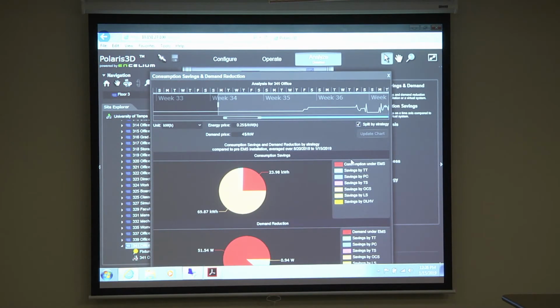So this looks pretty good. So 3/4 of this is savings for how far back I went for that room to where I'm at right now. So 3/4 of this is savings, right? So the occupant sensor you can see is saving the most energy right here in this portion. And I can do percentage too, I believe. Well, in this portion here, you can enter the energy price. So you've got demand price and energy price you can put in off your utility bill, right? And you can model them also using the different units, and it can give you a report with what's been done. So this is from August 20th to right now is when I ran this one for.